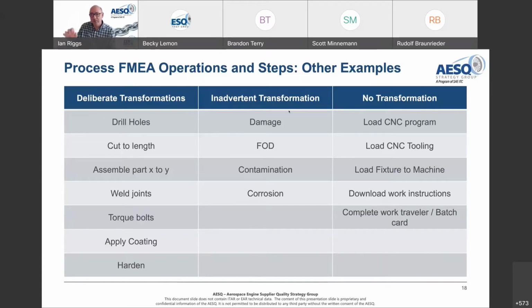For a measurement system, the real key things where you could legitimately put something into your FMEA is when you load it onto the CMM, you could damage it. It could pick up FOD. It might become cleanliness issues, etc., because you're handling the part. Those sorts of things would be legitimate to have as a line item.